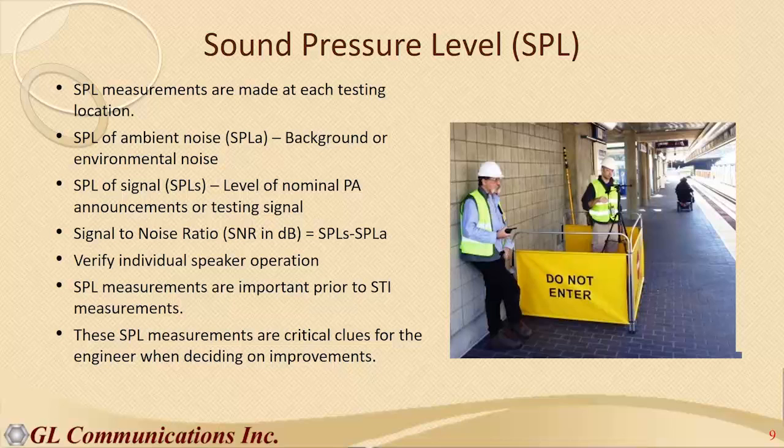Now, when we get into STI measurements, or speech transmission index measurements, it's going to be pretty obvious if a speaker's not working when you start reading these values on the STI. But this is a good way to do a verification on all speakers that they're operational. When the field crew's there, it's a good idea to do. And the SPL measurements are important to take prior to doing STI testing. Why is that? Because STI testing needs to have the SPL at a certain level and so forth.